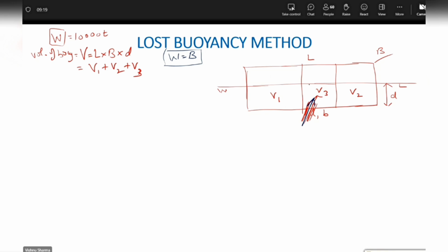When this compartment gets bilged, it first gets filled up with seawater up to this level. That is not the final, I'm saying. Okay. Now, tell me, guys, if the water has come into the compartment, and now the vessel rolls or pitches, will this level inside the compartment remain the same, or will it change with the rolling, pitching, and movement of the vessel? It will change with the rolling and pitching.